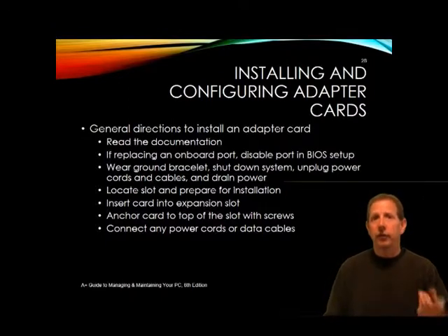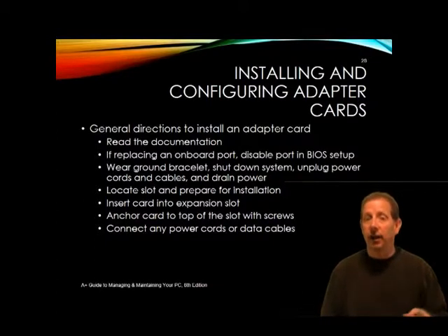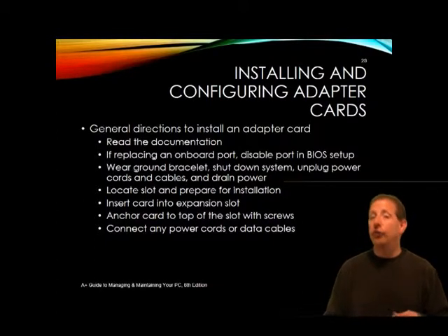When you're all done with that, insert the screw that anchors the card back into the slot, and be sure to use the screw that you took out. If it's not present, the card can creep out of the slot over time. And when that happens, you might end up getting a short circuit and actually destroy the card or the slot in the motherboard. Connect any power cords or data cables that the card might use.